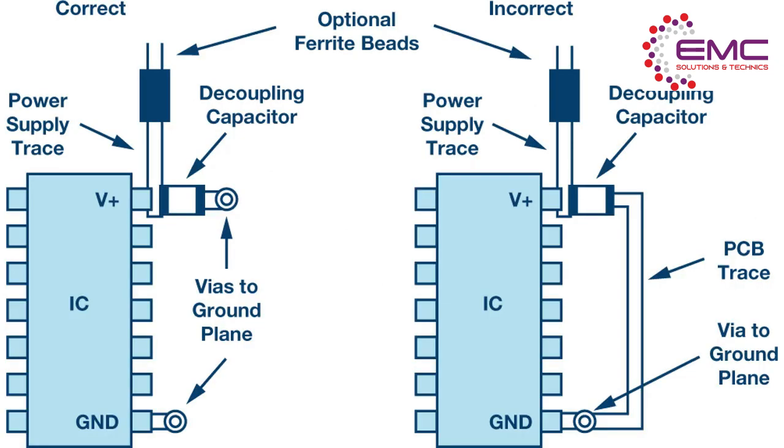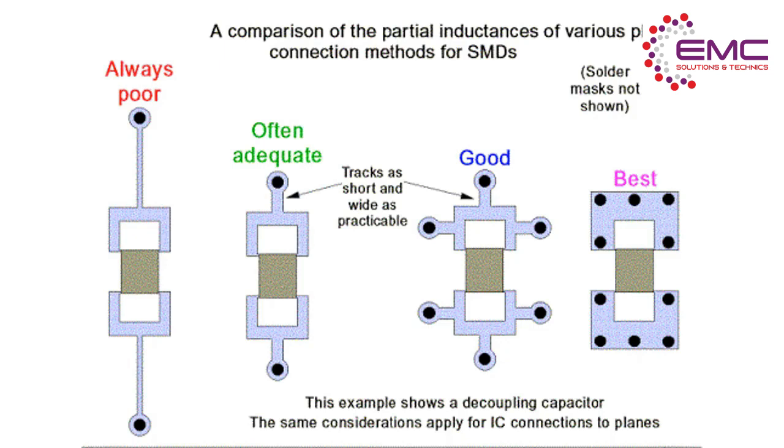Decoupling capacitor. Any noise on the power supply tends to alter the functionality of a device under operation. Generally, noise coupled on the power supply is of a high frequency, thus a bypass capacitor or decoupling capacitor is required to filter out this noise. A decoupling capacitor provides a low impedance path for high frequency current on the power plane to ground. The path followed by the current as it travels toward ground forms a ground loop.